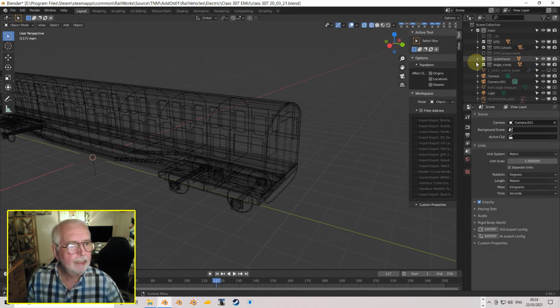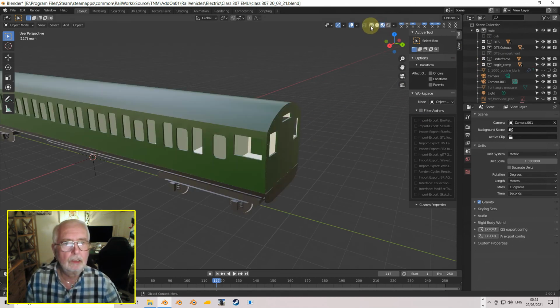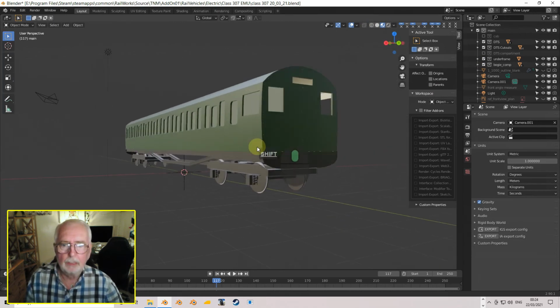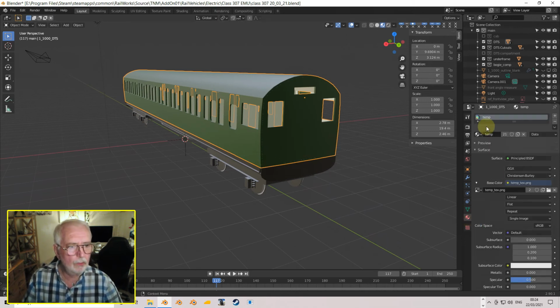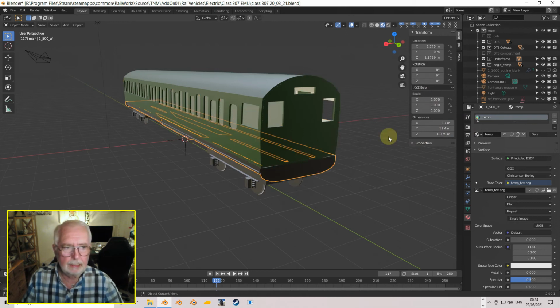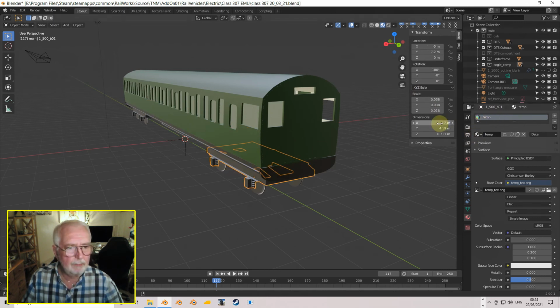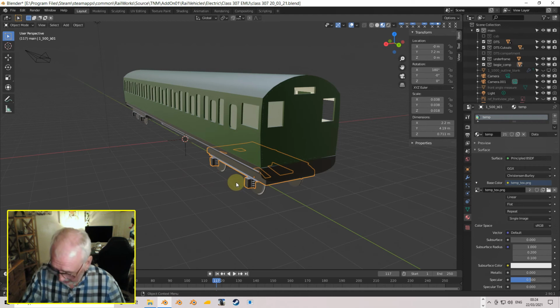So let's have a look. Anything else we need to think about? Let's come to our material mode, and just going to go through things here. Right, okay, so there's the vehicle. Let's have a look. It's got the temp material on, that's fine, and all's well here with the scaling. Yeah, temp material, that's fine. That's fine. Temp material, the scaling, it's not been scaled yet. When we imported that, the scaling wasn't reset, so I need to do that.